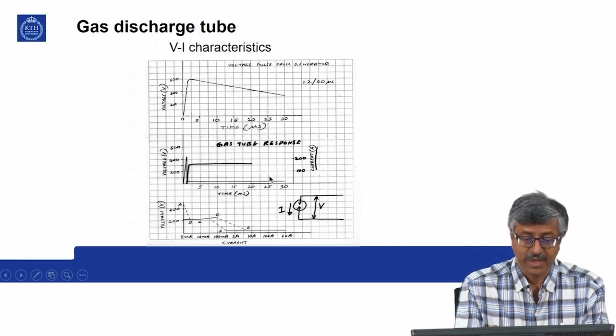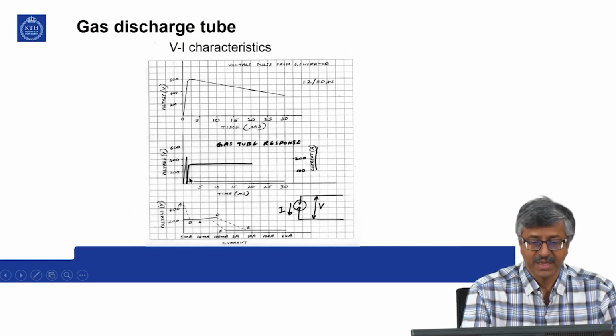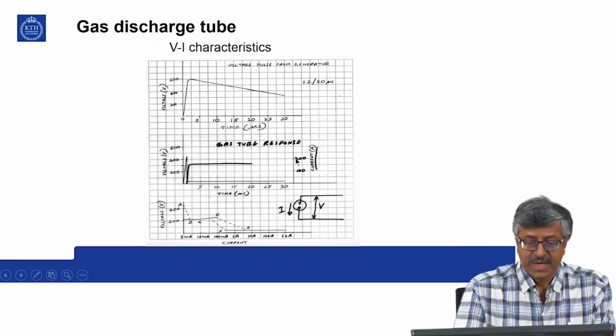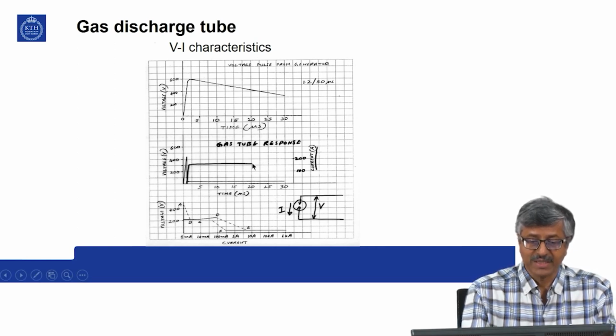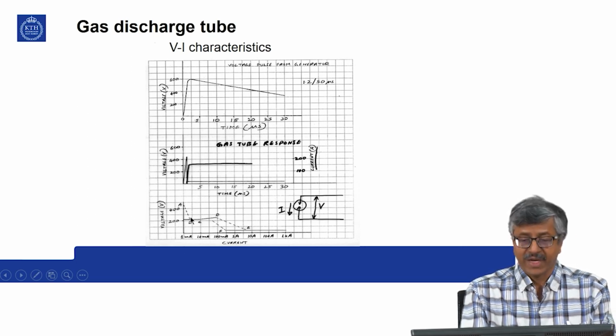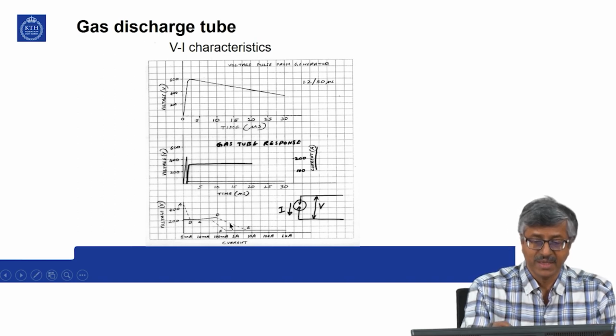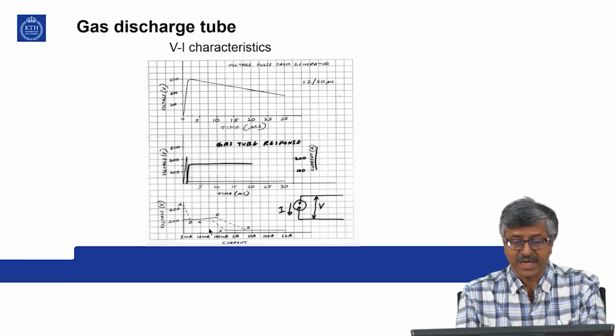So, this is the arc voltage, and at this point a current will be initiated, and that current rises up and it is shown over here. So, this current is quite large. Then for the gas discharge tube to turn off, the current has to come below a certain threshold value. So, this is the volt current characteristic of a gas discharge tube, and it is a representation of the same effect as per some other choice of axis, that is voltage and current.